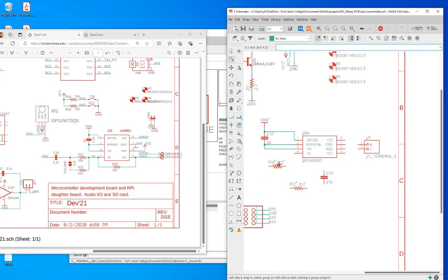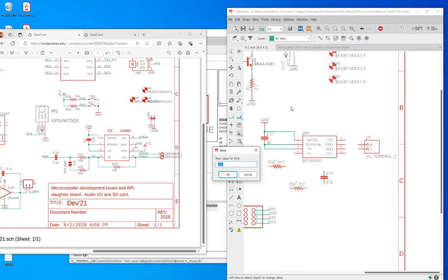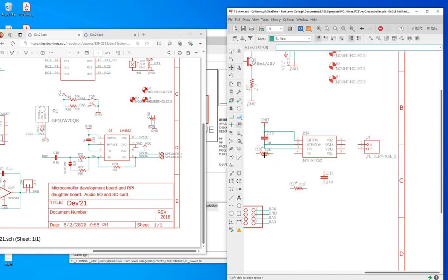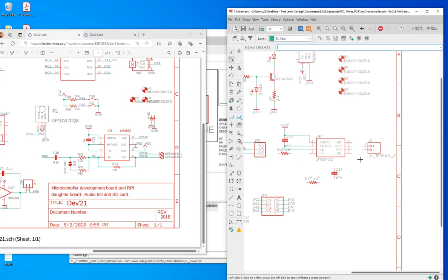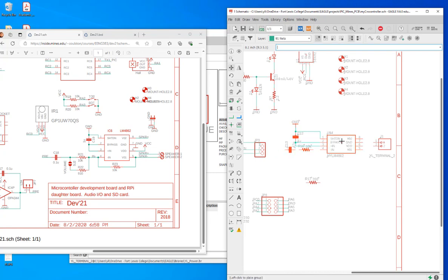And you need a resistor. I believe the value is 10K. Okay, and place it here. And have another capacitor here. High pass. And this one, put it at the edge. Again, this will be provided to you, okay? So you can directly use this one here and do the connections.